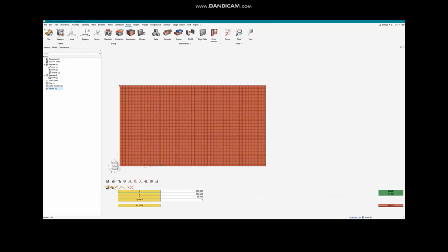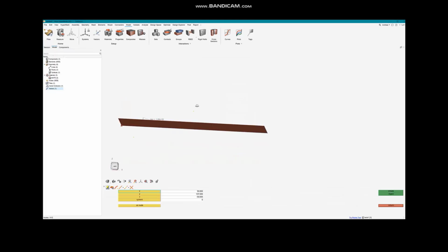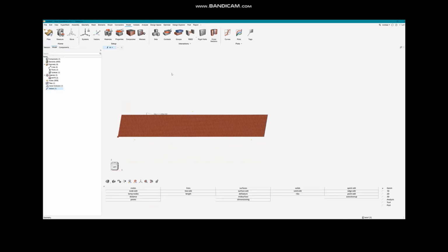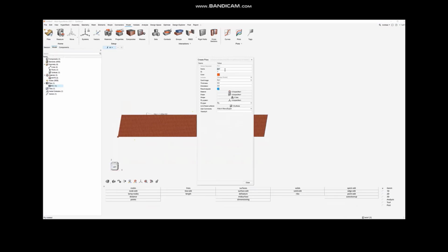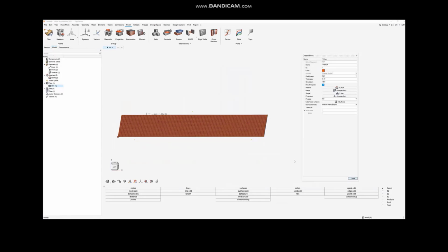But before that, let us make the test rig, the coordinates, the nodes for the test rig, and then we can start with the plies. As you can see, I define 3 plies, one in 45 degrees, one in 0, the unidirectional, and one in minus 45 degrees.